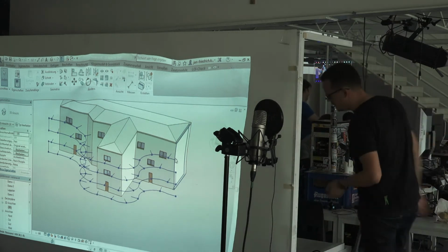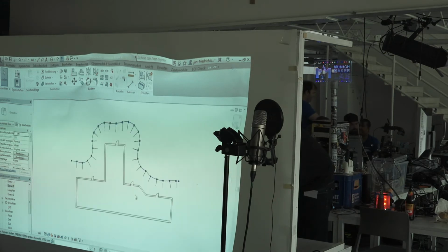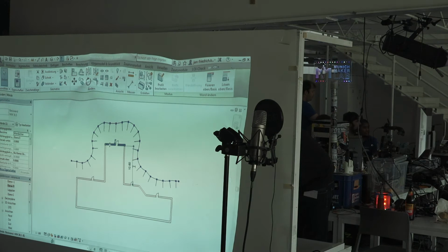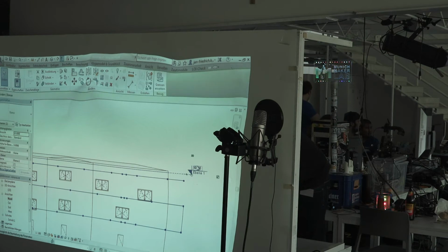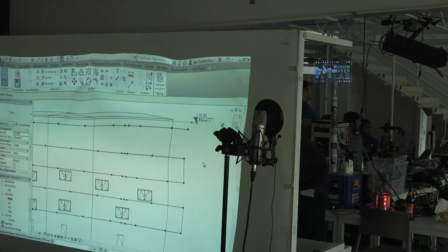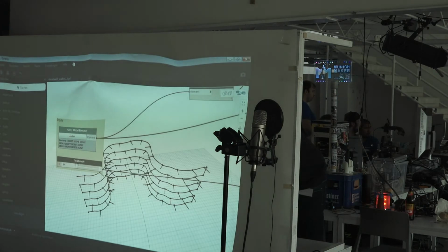And it's a dynamic tool. So when you do a modification in Revit, of course, the tool, so the flight path, adapts to the modification. You can change the wall, the tool changes, or even you can change the height of the building. You can see that the flight paths are generated dynamically. It takes a while, but in general, we have the more or less optimal flight route. And for example, I changed the focal length in our Dynamo script. 24 millimeters is quite wide.